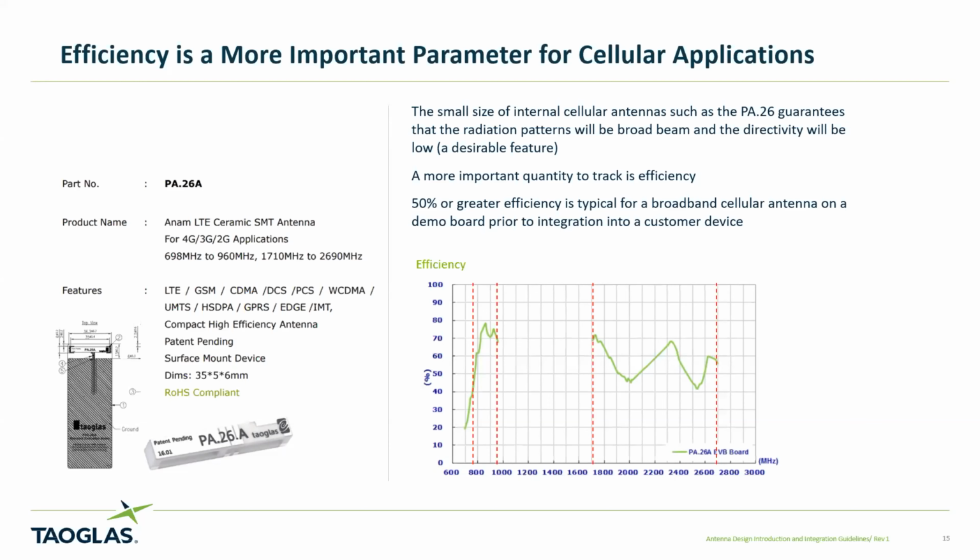Okay. So no antenna is going to be perfect. Even if you design a great antenna and you've only got 1.5 dB of conductor losses, mismatch losses, coupling losses, you'll have a minus 1.5 dBi omnidirectional antenna, if you could design that omni antenna. And that is what you lose in a link.